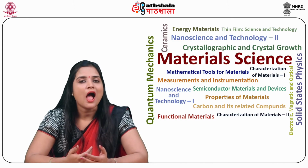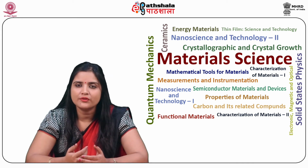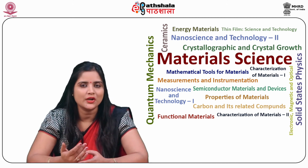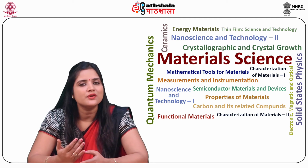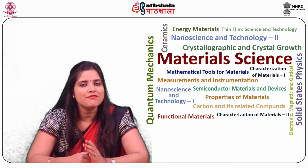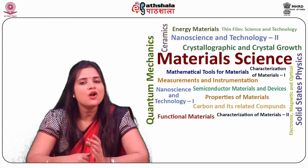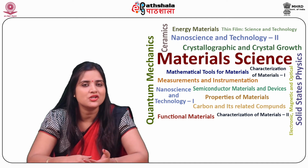An op-amp has two configurations, namely open loop and closed loop configurations. In open loop configuration, the op-amp functions as a high gain amplifier in three configurations: differential amplifier, inverting amplifier, and non-inverting amplifier. In all the three open loop configurations, any differential input signal which is slightly greater than 0 drives the output into saturation because of the high voltage gain of the op-amp, which is nearly infinite.